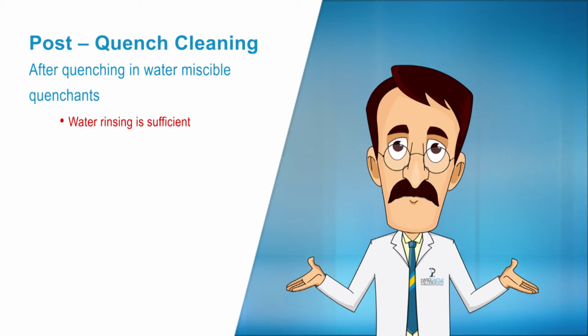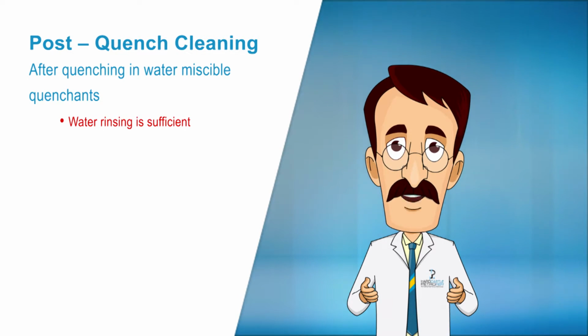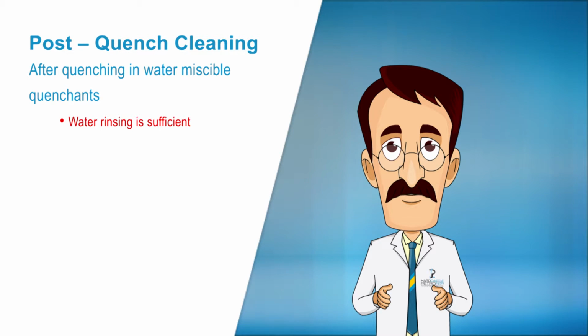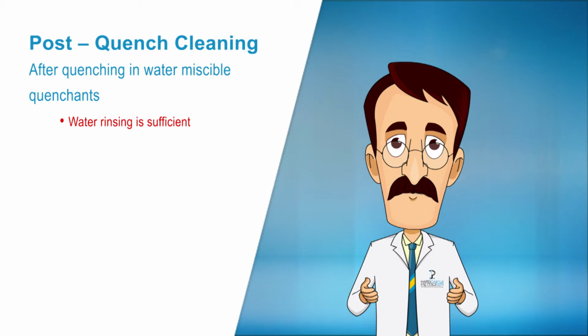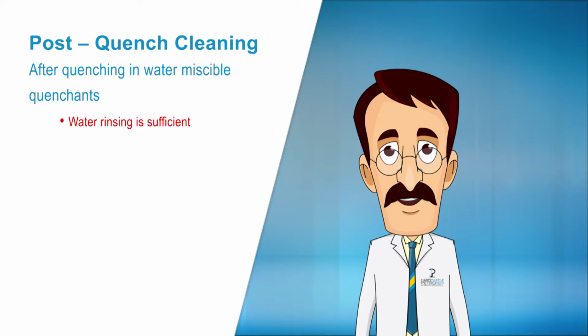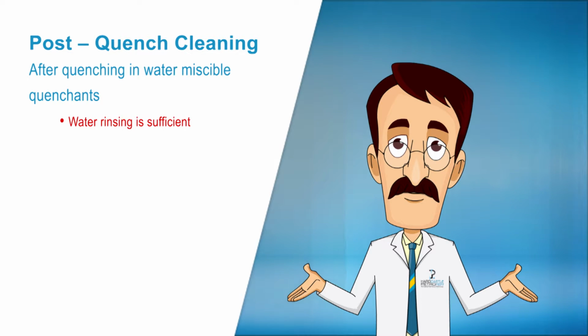HARDCASTLE Petrofers quenching oils will produce hardened components with a bright finish, provided, of course, there was no prior surface oxidation. The components are suitable for further treatment, such as electroplating, without problems. Oil residues do not burn into the surface of the metal and therefore can be easily removed.